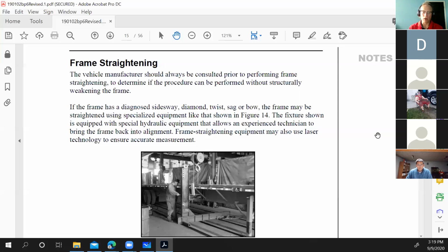One thing I loved the air arc for is changing dolly legs. If you had a way to support under the nose of the trailer, so it was on dolly legs, and well, I need new ones, so I'd support the front of the trailer, just lift it off the dolly pads just that much off the ground. You could essentially arc off the old dolly legs, leave all of the brackets still attached, and then you just bolt on the new ones and then just re-weld the brackets. So it has its purpose and it works really well for what it does.